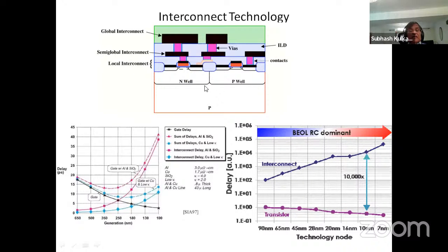Now, if you look at this chart, this is the cross section. You have the transistor built at this lowest level, orange color, 2 transistors. And you have contacts using tungsten, contact over tungsten here, another contact. And this is the first metal, black one, which is thin.